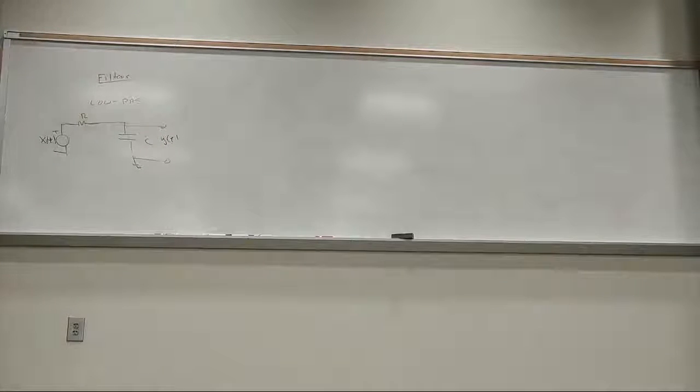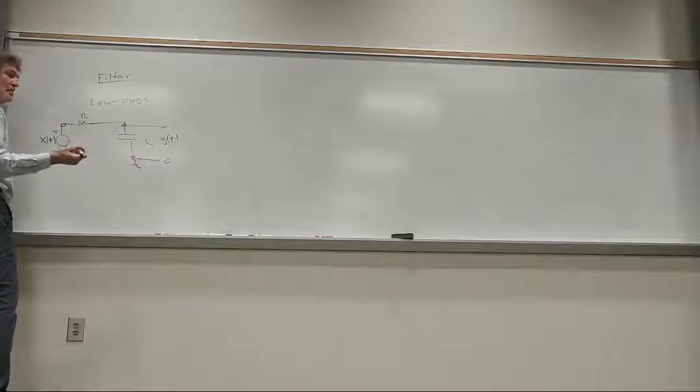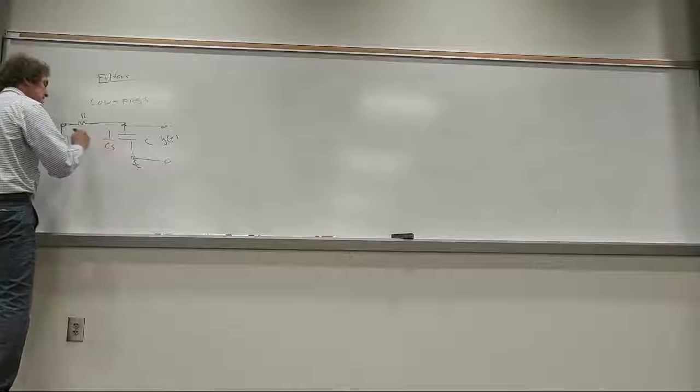And if you look at this, you could do it in the continuous time domain, but it doesn't help. It's best to find the transfer function for this system in the frequency domain. And the S domain, frankly, is the best way to do this. If you do this in the S domain, the impedance of the capacitor is 1 over CS, right?